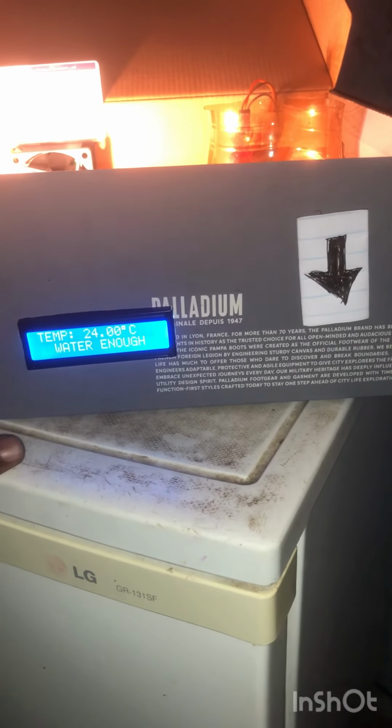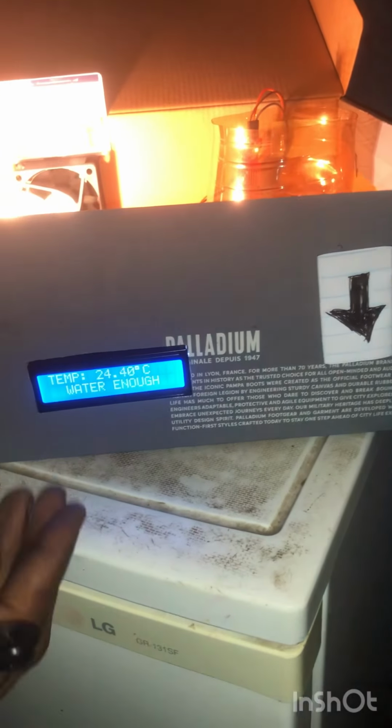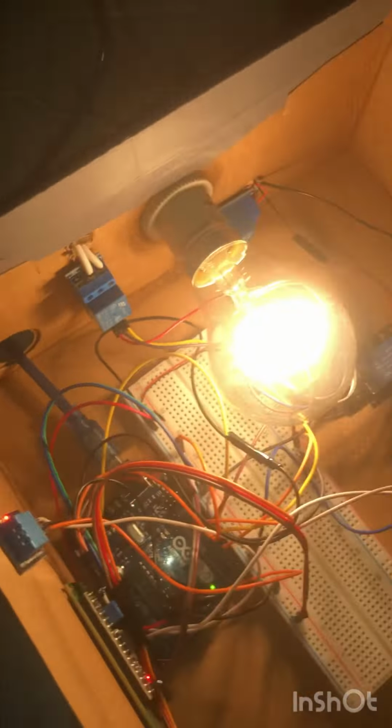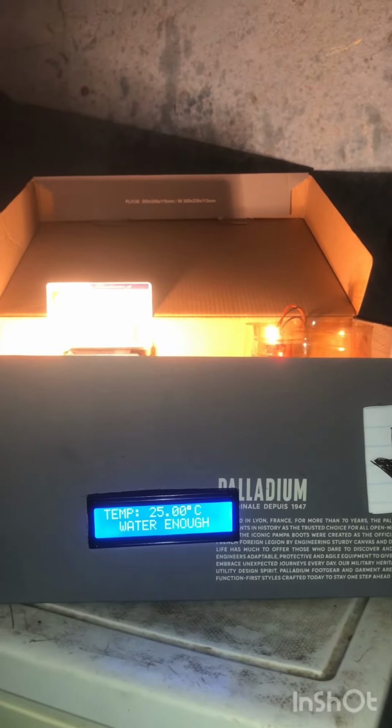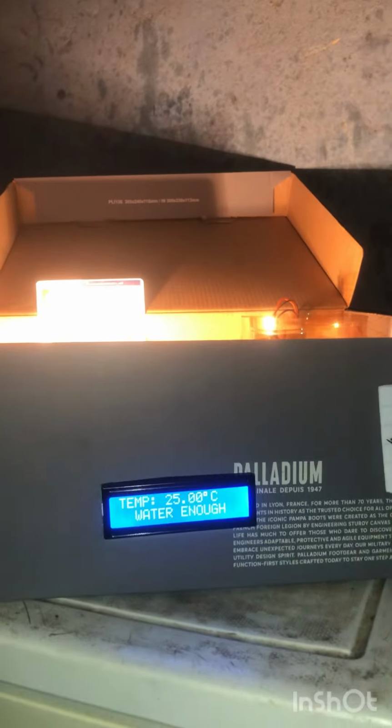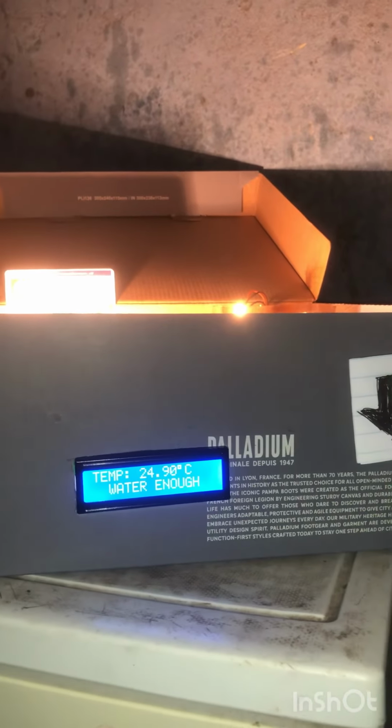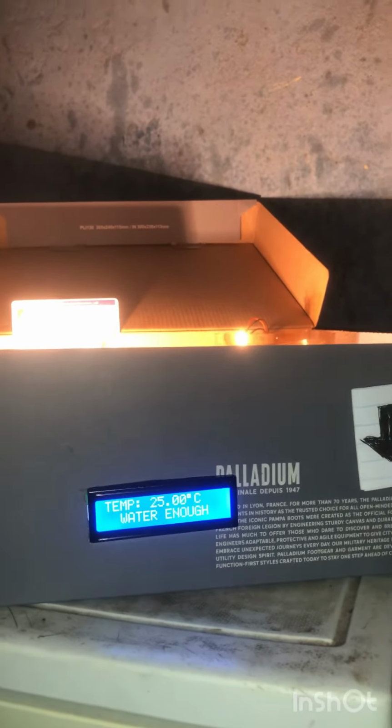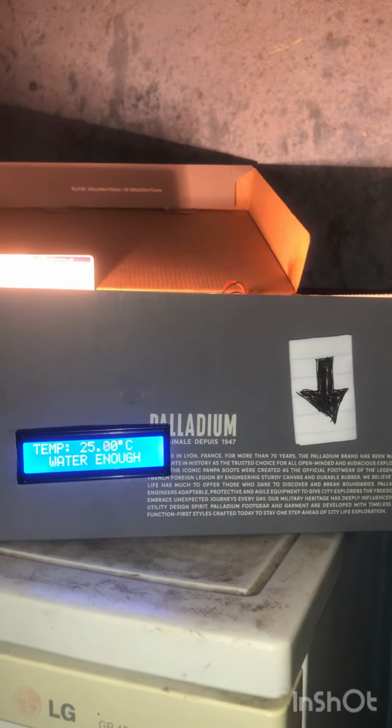But now that the heat source is on, you can slowly see the temperature rising, and as soon as the temperature hits 27 degrees, it is said to be a normal or the desired temperature. Therefore, in the normal temperature situation, we can expect that there will be no control mechanisms except the window being slightly open. The fan will remain off and our heat source will turn off.